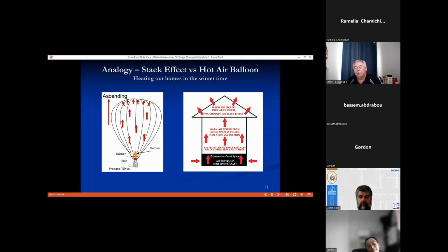That crack, in the majority of cases, is only about maybe 1/16 of an inch wide. But at 1/16 of an inch wide, it means that every 16 inches, we have an equivalent opening of 1 square inch. When we measure the crack around the whole perimeter of the basement, that opening could represent the equivalent of a hole that's about 1 foot by 1 foot, where the radon can infiltrate into your home. A lot of times we don't see that crack because we have insulation on our foundation walls and finishing, gyp rock and stuff like that. So a lot of times that crack is hidden behind the insulation, but it's there. And that's one of the prime locations for the radon to get into your home.